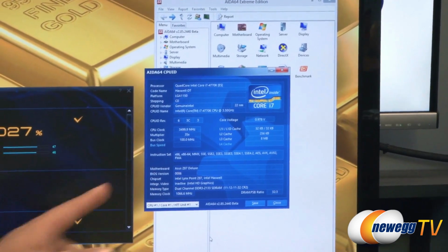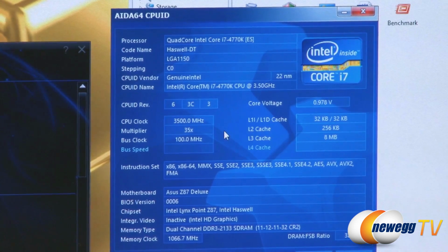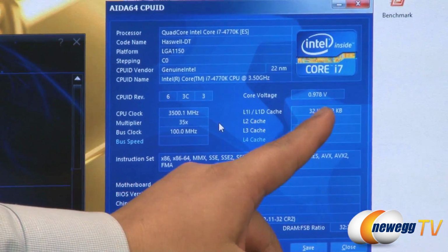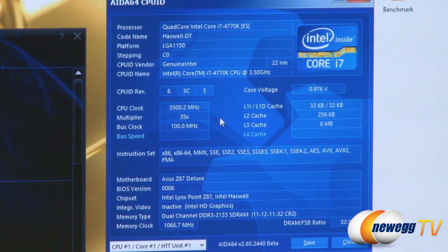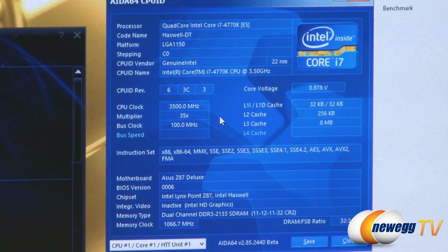So we can see here one of the great things is that because of our use of adaptive voltage, the CPU frequency goes down when the system is under idle, right? And what does the CPU voltage do? It also goes down. So we're really getting that great power efficiency and that power reduction, as opposed to if you were doing it probably manually, you're going to force that CPU frequency to run always at that frequency, and the voltage tables are going to be significantly higher. And that, as you mentioned, could even lead to CPU degradation over time?